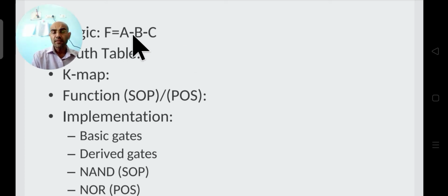Now consider that there are 3 variables, identify the number of outputs and then write the truth table for it, with 3 inputs and 2 outputs. The 2 outputs will be difference and borrow, and the 3 inputs will be A, B and C. See what the entries of your truth table are, following the same logic we saw in the last slide for the half subtractor.